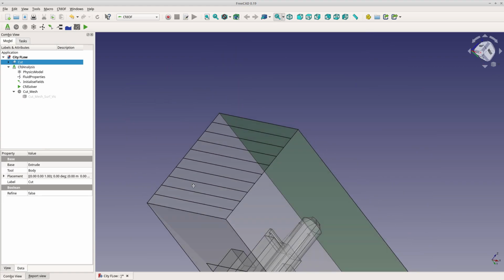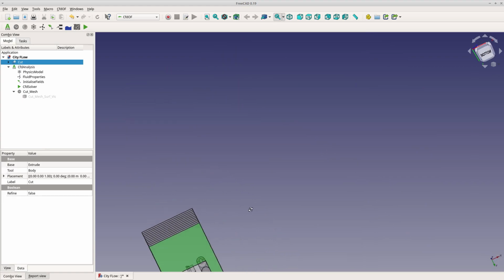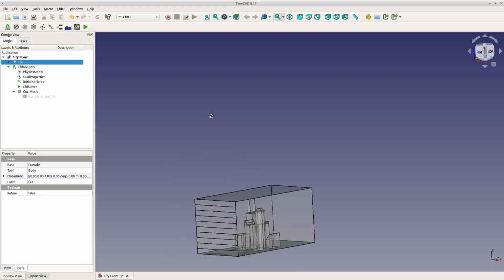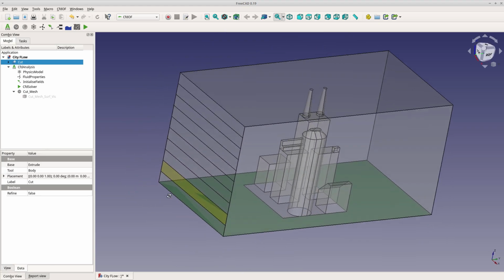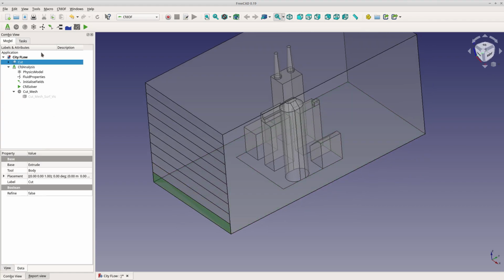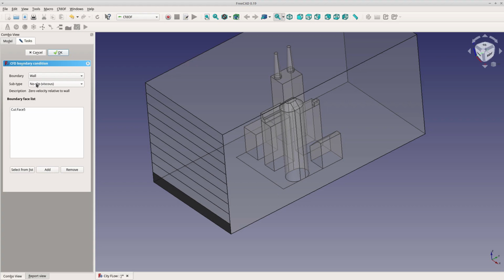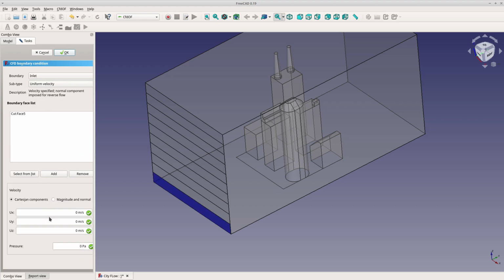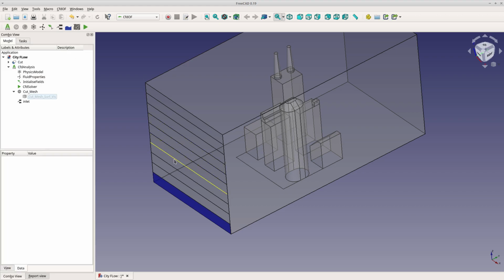And yeah, I think all of our faces are highlighting pretty well. So I think our graphics anomaly is just an anomaly, I'm hoping. Let's grab our first thing. We're going to say an inlet, and let's say that this is 1 meter per second at 100 kilopascals or 10,000 pascals. We're going to say OK to that.